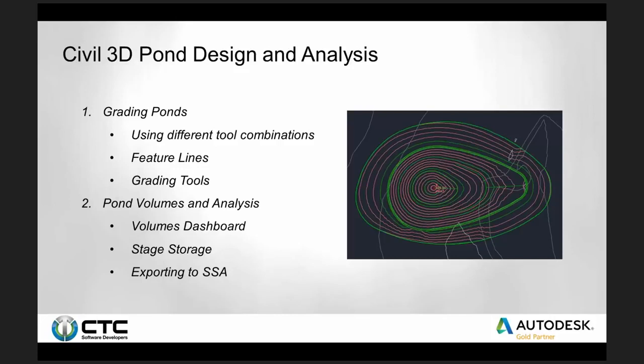And then we'll introduce the Stage Storage tool. It's been around for a while. Maybe some folks aren't used to it or aware of it though, and I'll show how that works, and that's to get not just an overall bulk storage of your pond, but a staged storage. And then we'll look at exporting that to Storm and Sanitary Analysis, and I'll just do a brief import of it as well into SSA. I won't spend much time there, but just show you where and how that pond definition can be imported into SSA for further analysis with your storm network there.